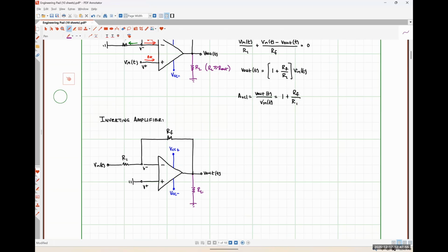So for what it's worth, if you look in your notes for the positive feedback amplifier, actually, I was thinking of the open loop amplifiers where I give you a specific input-output relationship for the inverting comparator and the non-inverting comparator. We didn't really do one of those for the positive feedback circuits, the Schmitt triggers, because really the thing that's causing the change is the upper trigger limit voltage and the lower trigger limit voltage. So comparing the input voltage to those values tells you whether you're going to have V out as VCC plus or V out as VCC minus. So, all right. Applying our op amp rule, noting that these currents are 0.